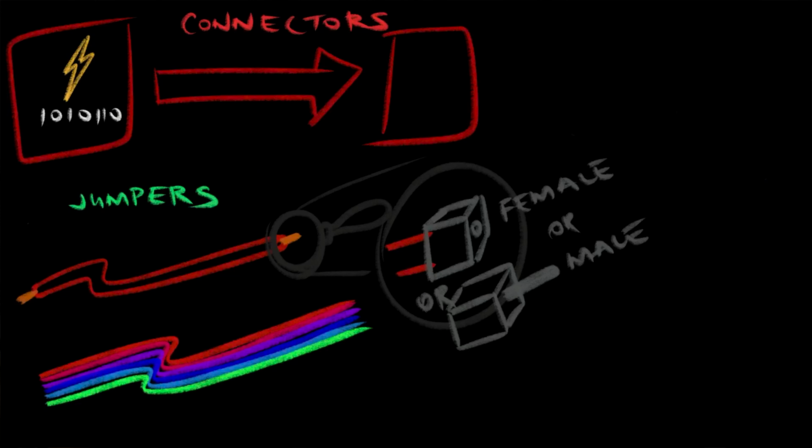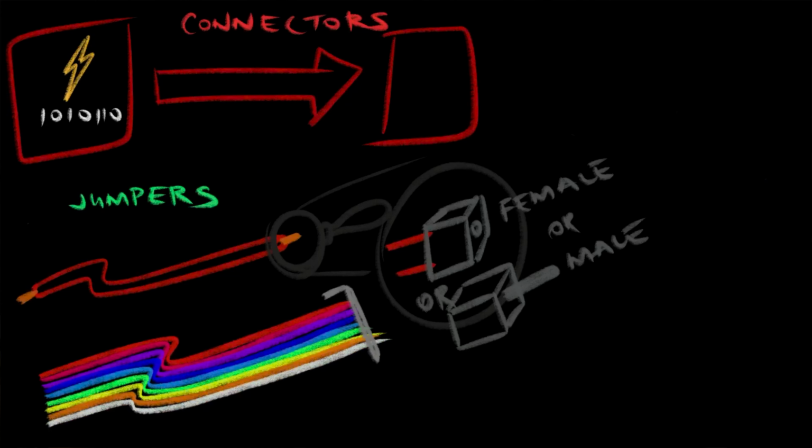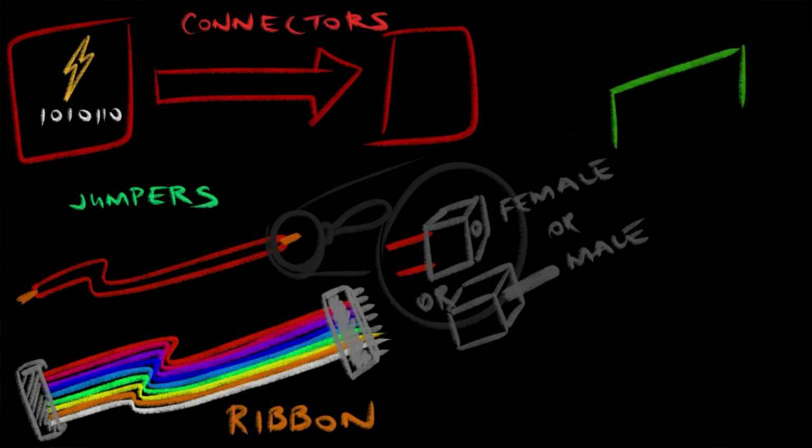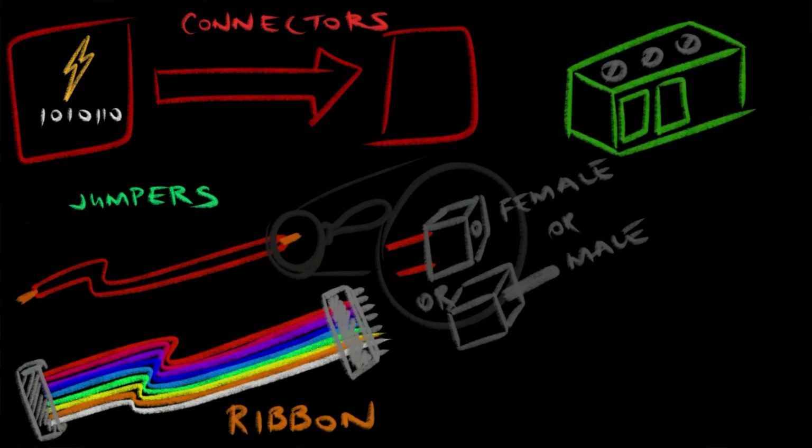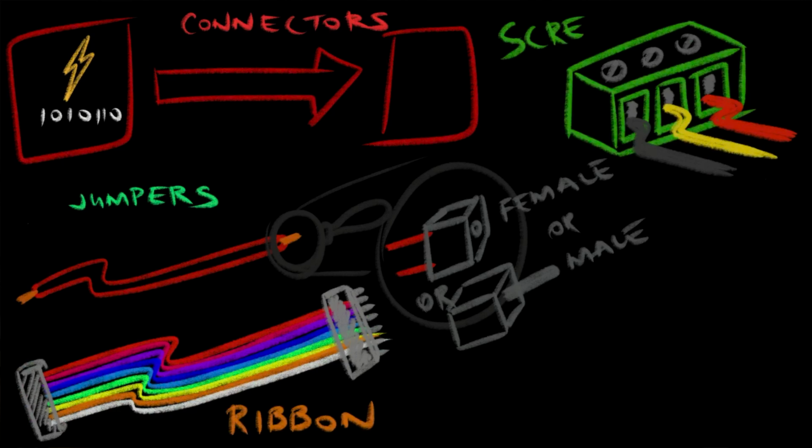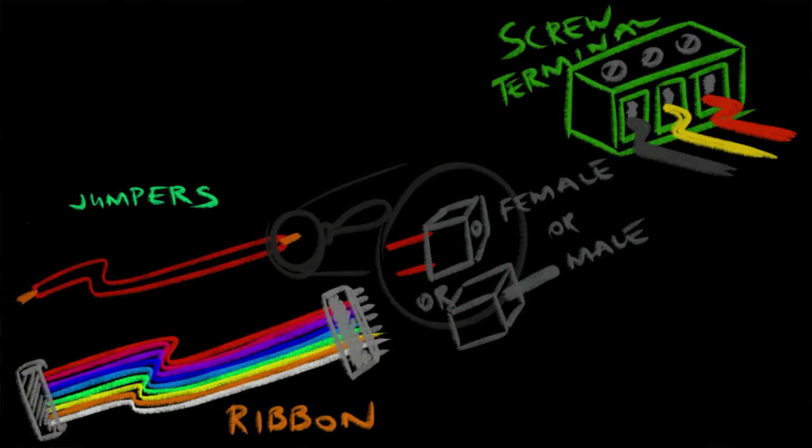These are commonly used in breadboard circuit prototyping or testing, as they easily and securely slide in and out of a breadboard. If they are to be used on a printed circuit board or strip board, a more secure connection source such as a screw terminal may be needed. Screw terminals need to be soldered onto the strip boards or PCB permanently. However, the jumper wires can be slid into the individual terminals and held tightly in place with the use of a screw. When the connection is no longer needed, the screw can be untightened and the jumper released.